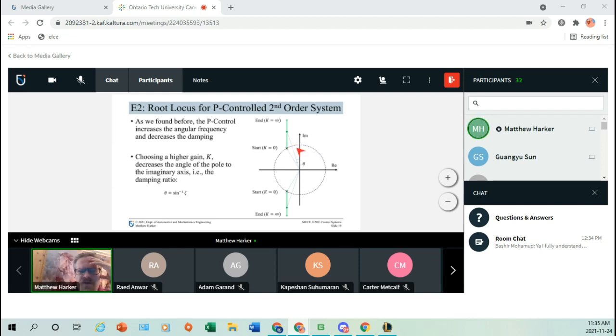So we end up with the real and imaginary parts of the poles being the damped natural frequency, or the resonant frequency. And then the damping ratio, well, they're both dependent on damping ratio and natural frequency, right? The two-parameter normalization. But again, if you move this around on this axis, the root locus would look essentially the same.